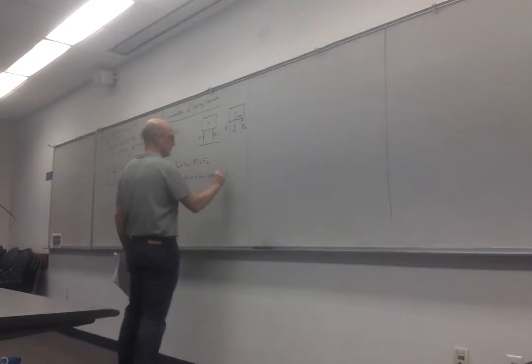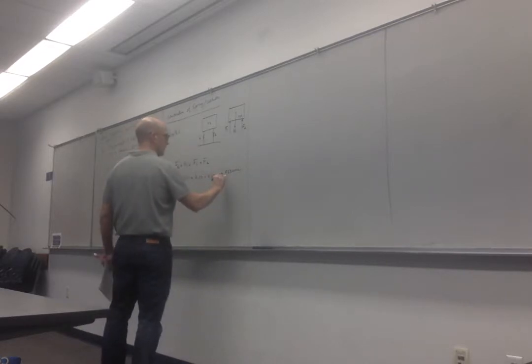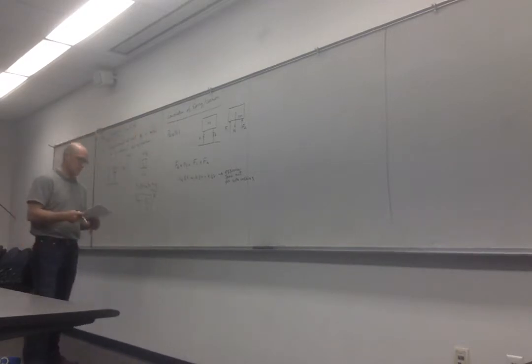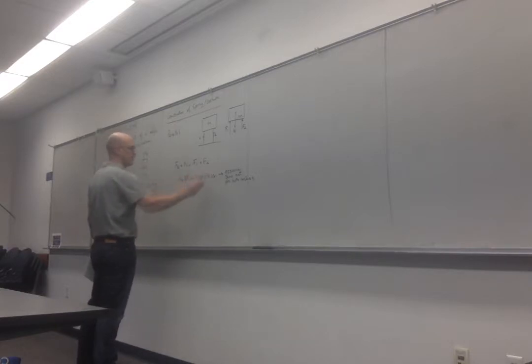Here we assume that we have the same material for both cushions. So that means if you have all of this, you need to understand that all of these displacements are the same. So they all simplify, and you end up with an equivalent K that is basically the sum of these K's, or in this case, just 2K, like this.